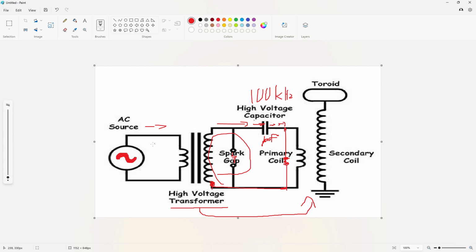But in general AC circuitry, both the wires are the same. There's no, like, this isn't AC1 and this is AC2, or this isn't line and this isn't neutral. Now you might see that sometimes depicted on a schematic to show you how the plug is oriented when you plug into the device, but that's irrelevant when it comes to the other side of the transformer. The other side of the transformer doesn't know about this.